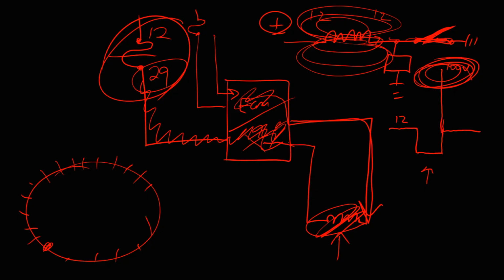When I unplugged it, I had battery voltage and like 16 or 17 volts on the other side of the fuse with it disconnected on another Ford, just to prove my concept on where it was coming from. It wouldn't run. Key on, engine off, the car wouldn't run. With that blown main ECM fuse, I had no comm to the ECM, the car would not run. Truck would not run. Weirdest thing I've ever seen.